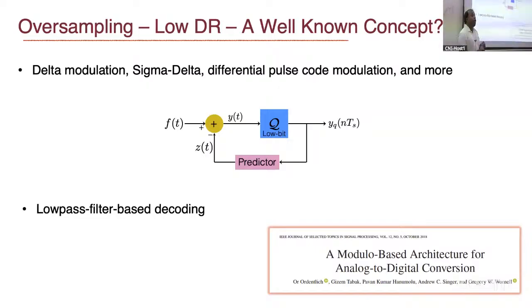So why are we doing all this oversampling and everything? What is the reason? We asked a question: can we sample a high dynamic range signal using a low dynamic range ADC? With modulo, we can do that. Why should we do oversampling? To reconstruct, essentially that operation called unfolding, right?